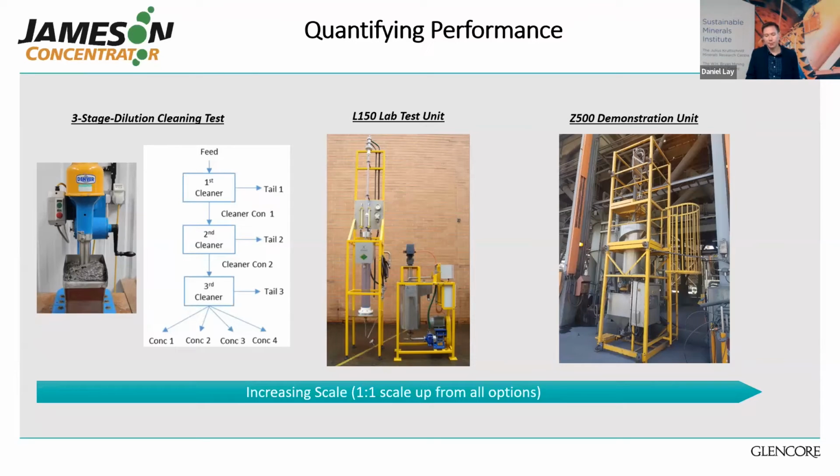Essentially, what we're doing is separating the material according to its floatability, with the most liberated material removed first, followed by the less liberated material, followed by the middlings material, and so on. Incidentally, this test was originally developed for coal for ash yield curves, similar to the float sink analysis they do for DMS. Thus, the output of the test should be seen as a function of the ore's mineralogy and liberation characteristics rather than of a particular operating condition.